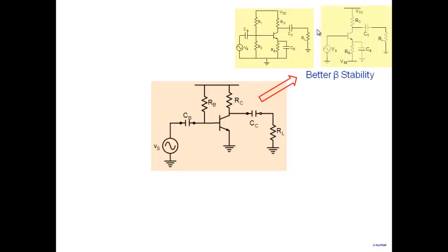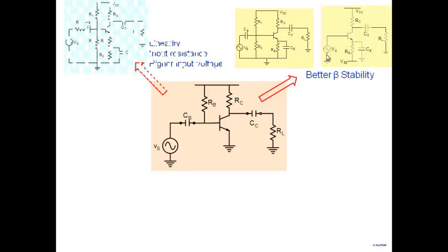Now, all three of them have certain problems. And in an attempt to overcome some of those problems, we arrived at this one. We said that the emitter resistance that we are putting here and here, a part of the emitter resistance, if we leave it unbypassed, it results in several advantages. It allows us to obtain high linearity, better swing, lower distortion, high input resistance, and higher input voltage you can apply, and the cutoff frequencies are also improved. So all those advantages come when you leave a part of emitter resistance which is unbypassed. Of course, what you're doing is you're sacrificing gain in the process.